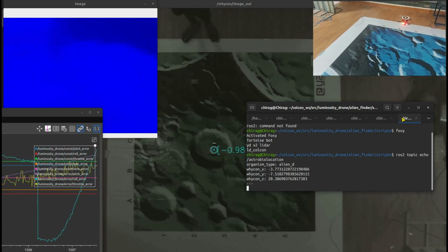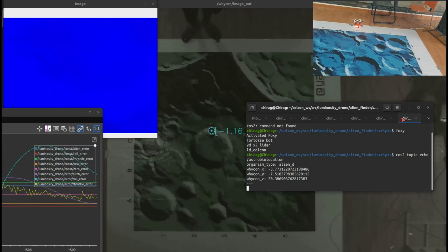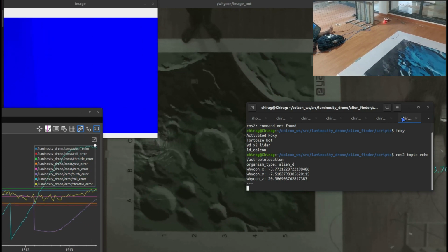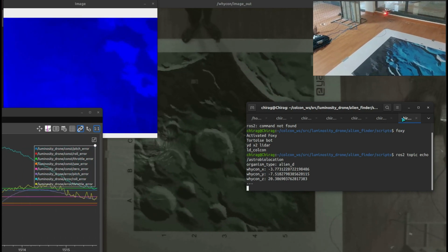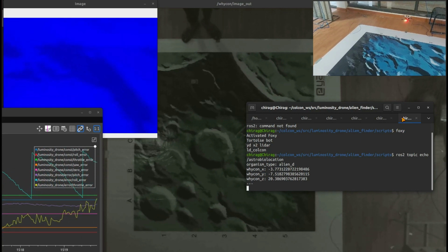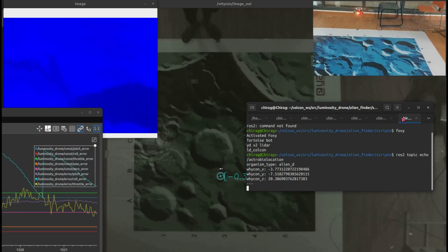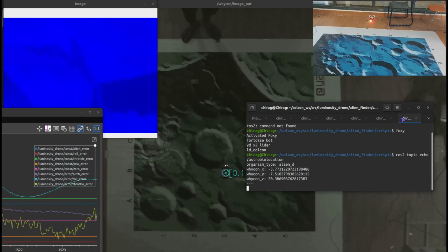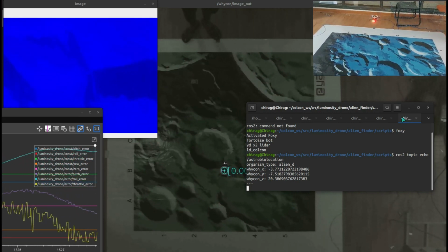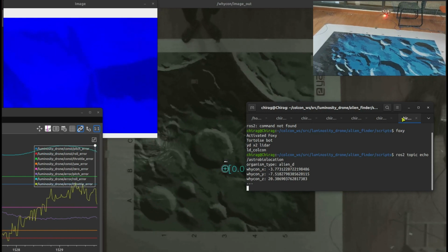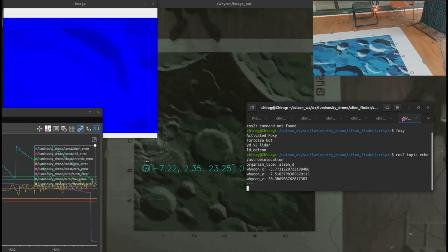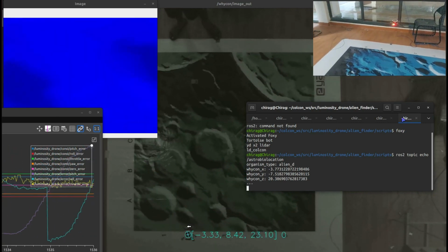The control loop was made sure to run at a constant frequency of 60 Hz. It was also ensured that in case the organism goes out of the frame of the drone camera, the drone would try to bring it into its frame again, and if it couldn't, then the drone returns to the position where it first detected the organism and would continue with its search algorithm. This would ensure that the drone doesn't crash.